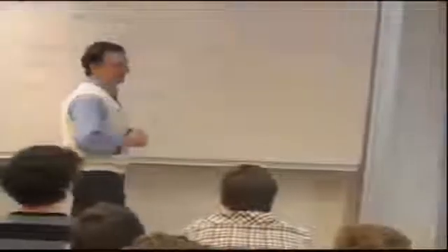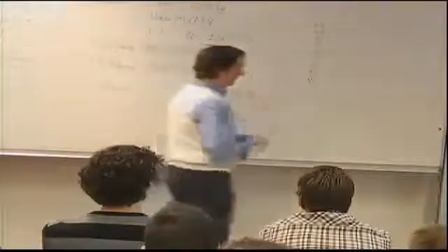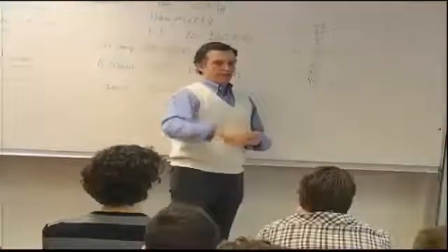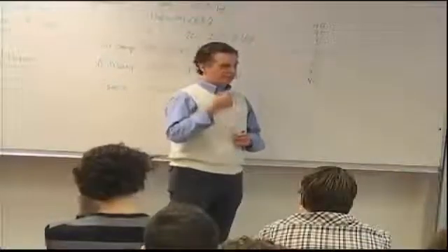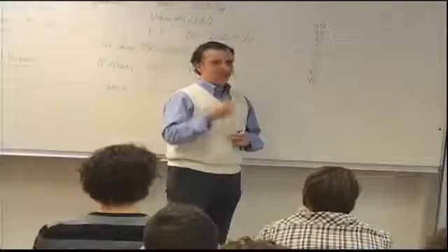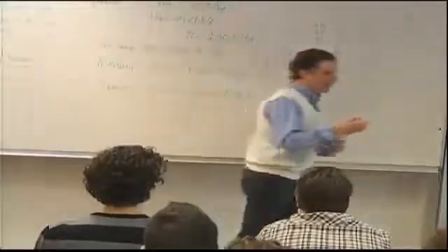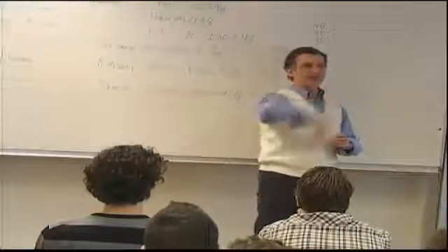These assumptions reminded me of one thing I wanted to say. I keep mentioning quasi-isotropic, and just for purposes of definition, it's also in the text in the book. One way to create quasi-isotropic laminates, or the best way to create a quasi-isotropic laminate, is to make sure that you have exactly the same number of fibers in every direction.